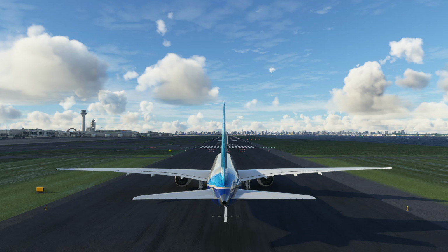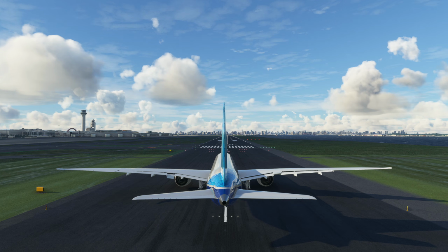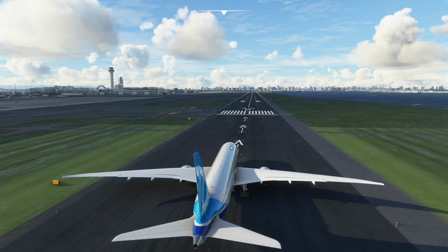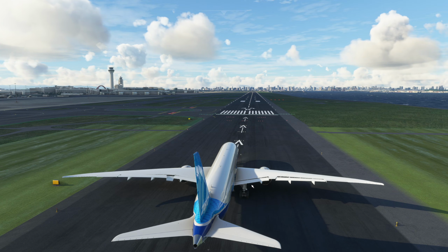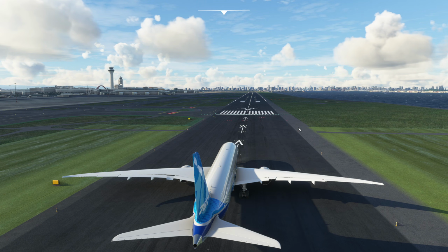Now you have a bit of margin, but once they're up, that's more drag, so that starts to degrade your takeoff performance a bit, so you don't want to be excessive with it. There's another problem, which is, of course, this aeroplane, as we roll down the runway, is going to try and point to the right. It's going to try and turn into wind because the wind is hitting the tail, pushing the nose to the right. As we also then keep the wings level, we're actually putting more weight on this gear, which again increases the drag on this side of the airplane, trying to weathercock the aircraft into wind, so it needs more rudder.